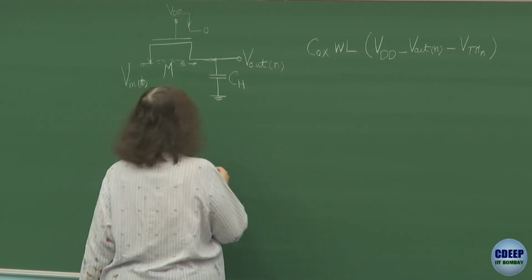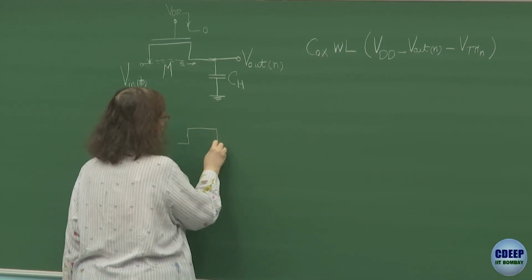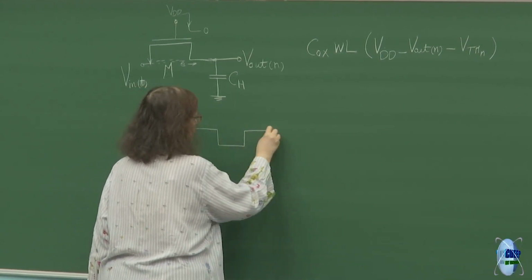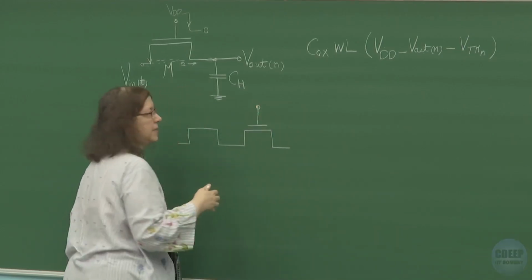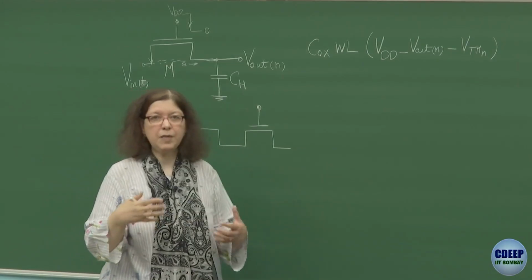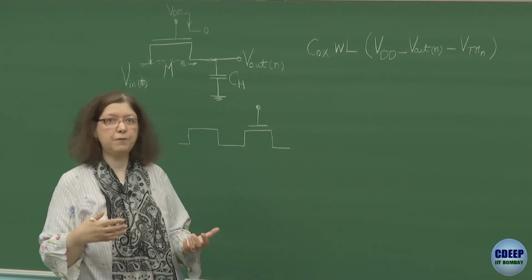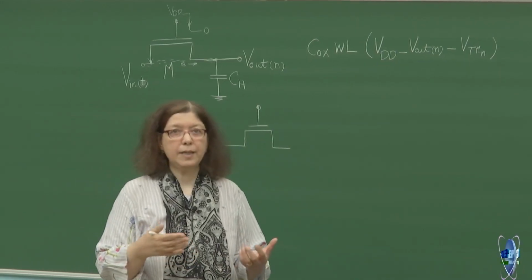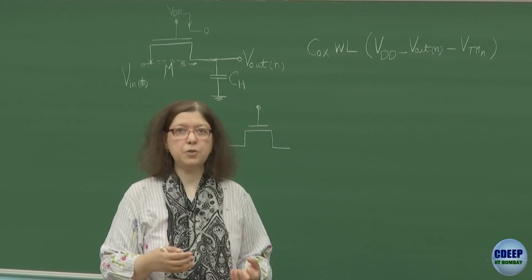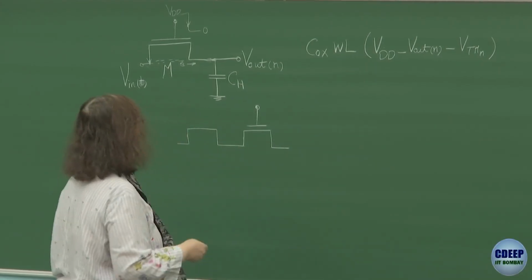And for that, one of the common ways is to imagine you have a dummy switch. This dummy switch effectively is a capacitor, which we keep, but we want to make it exactly the same as the switch. Therefore, we don't use a capacitor, we actually use a transistor of exactly the same type as the switch to divert the charge towards that transistor.